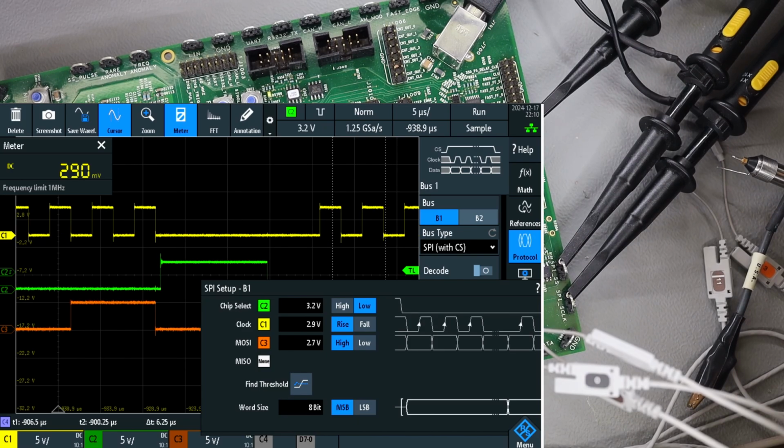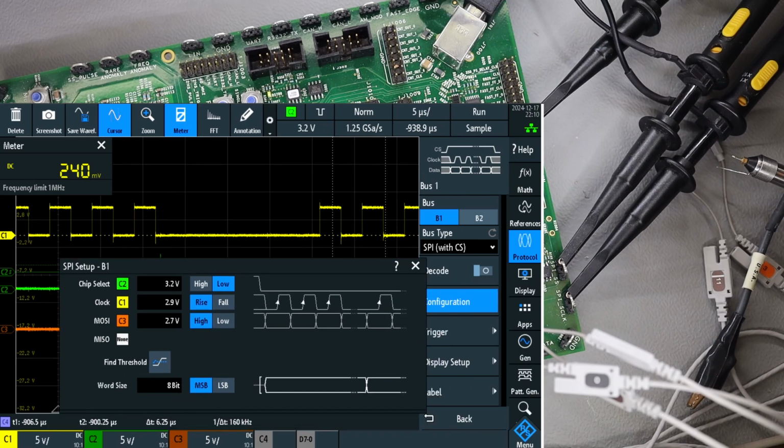It's pretty much obvious. If I do this, it will be incorrect; if I do it like that, it will be incorrect. Our CS polarity is low, and MOSI is normal active high, not active low. So this selection of the data is appropriate.